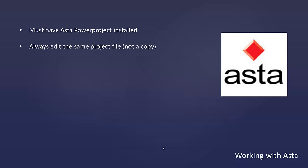The second note here, you always want to work from the same project, not a copy. So what that means is, if you created project 1 and then you saved as project 2, at this point it would be fine to work from either project 1 or project 2 because they're identical. But if you made the same changes to project 1 and project 2, adding a new task in both project 1 and project 2, it's not guaranteed that those two new tasks would have the same ID. It's the same unique ID in Asta, just the way that they assign those IDs.